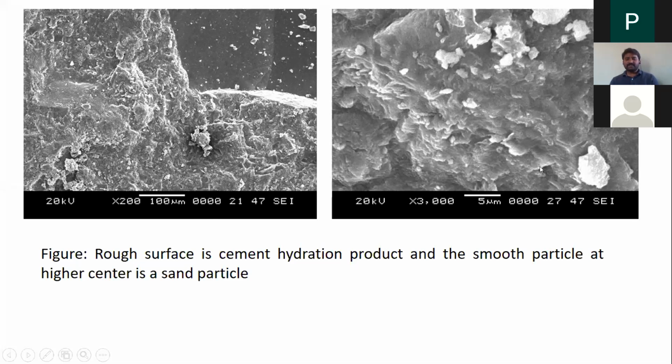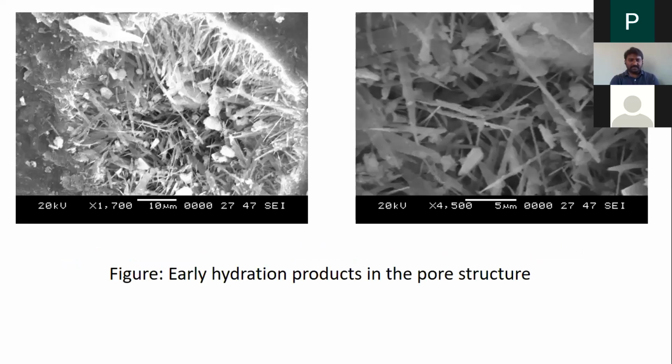Okay, so from this we can identify this is unreacted particle. This is calcium silicate hydrate, and in lower zooms we can see the sand grain. Beside that there is calcium hydroxide, the brightest part which appears. We will come to that, which is brighter and what does indicate, in a little bit of time. So this is how you see the secondary electron images.